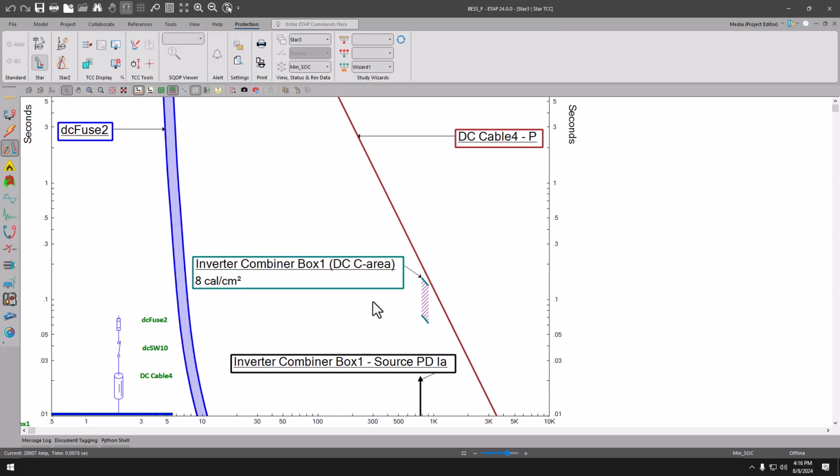Now, of course, this is very useful in the protection and coordination phase because, as you saw just a few seconds ago, in order to establish this reference curve, all I needed was a range of fault currents, which again, you don't need any arc flash knowledge for, and a couple of engineering assumptions for potential tolerances in the arc flash input parameters, which again, we can do with proper engineering judgment.